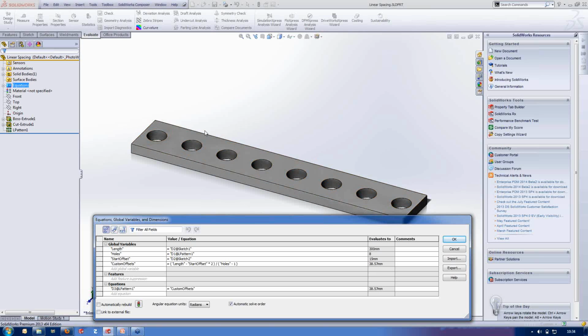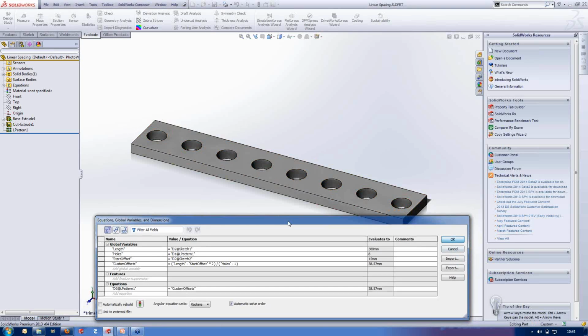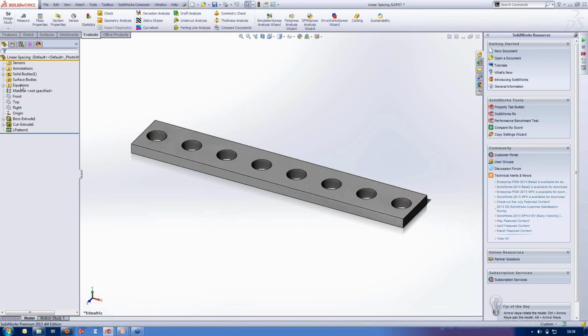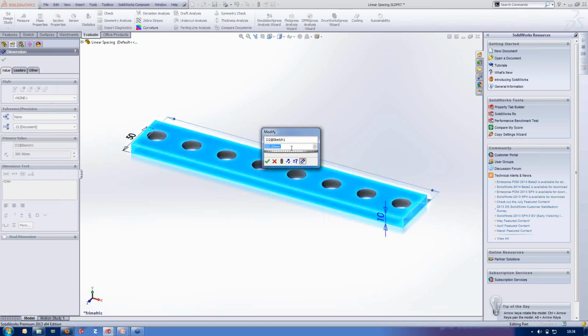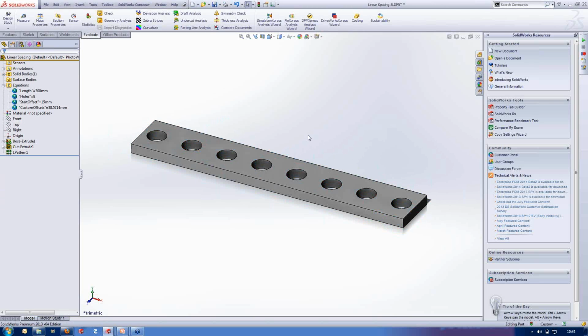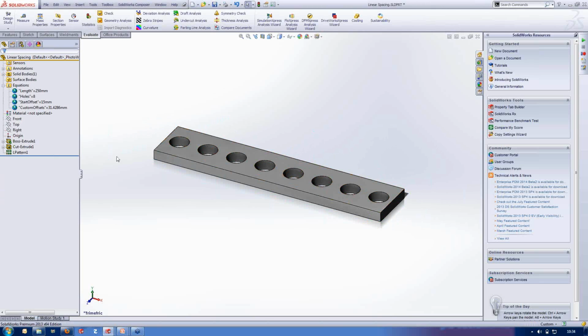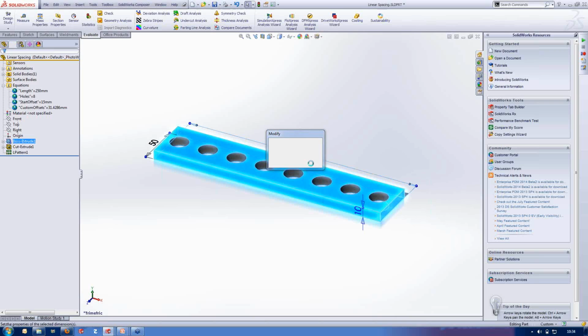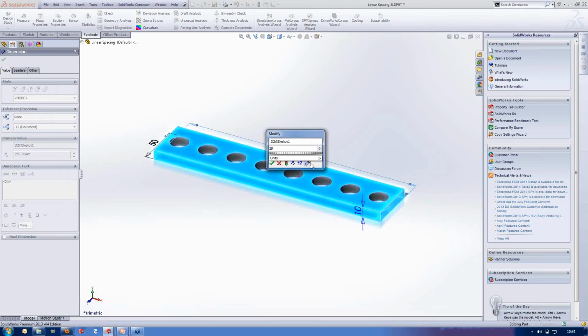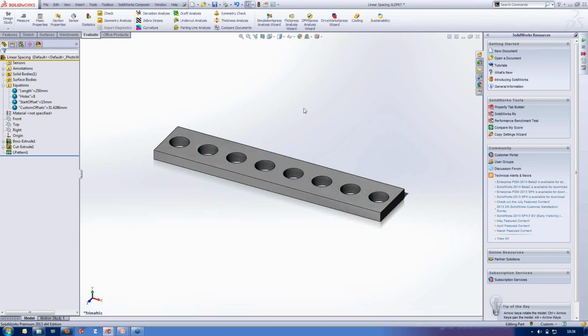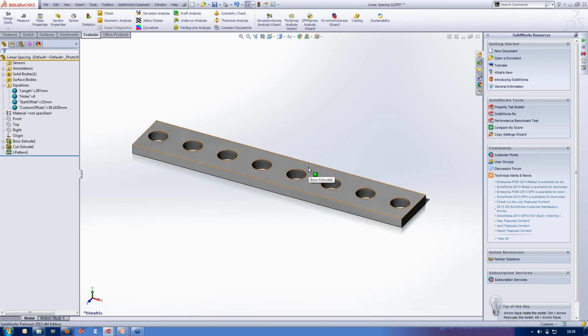So we want to calculate the gaps, so we take a hole off. And then I set it to custom offsets. Now, this is quite nice and quite friendly, because again, if I change 300 and I change it down to 250, it will bring all of my holes together. So I know very simply what my hole count is, and it becomes very easy to modify and make sure my gaps are all equal, all even, all the time. So it becomes really handy.